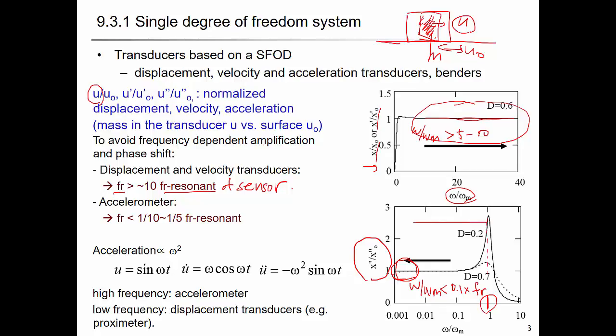What happens if your system resonant frequency matches with the accelerometer? Then their response will amplify so that you get a biased response. So in the measurement, you should avoid that.